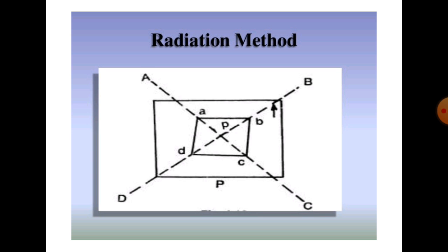Then fix the alidade, touching it at point P, sight the object A, and bisect the ranging rod at A. Here an imaginary line is drawn from P to A as a dotted light line. Clear?